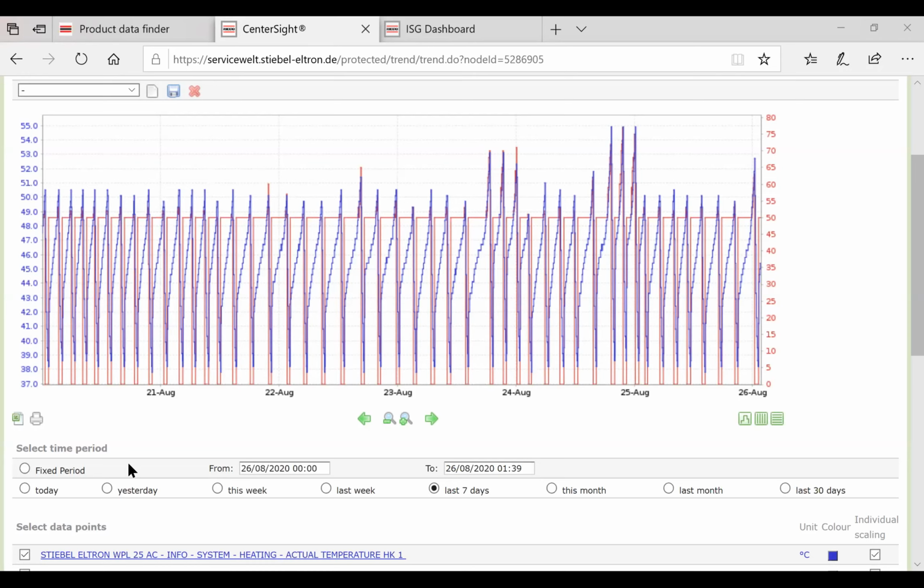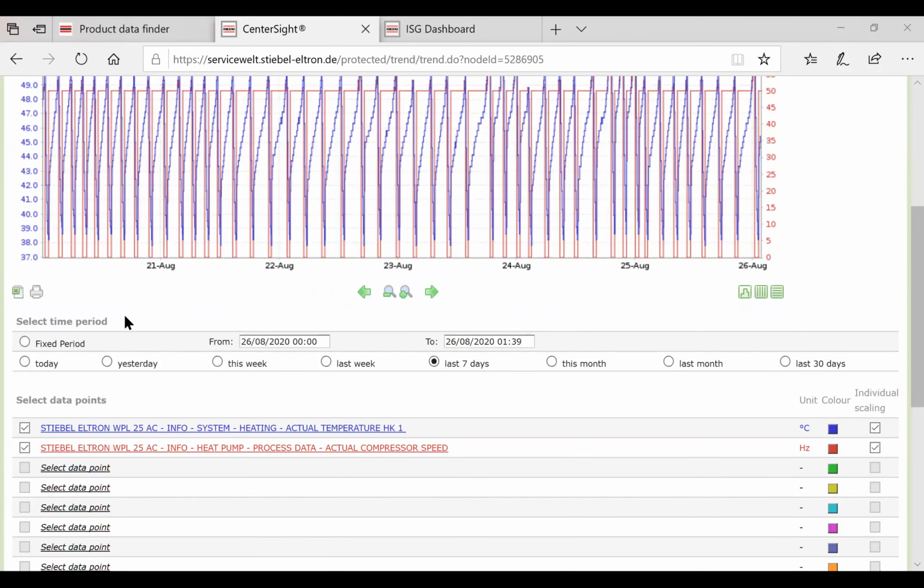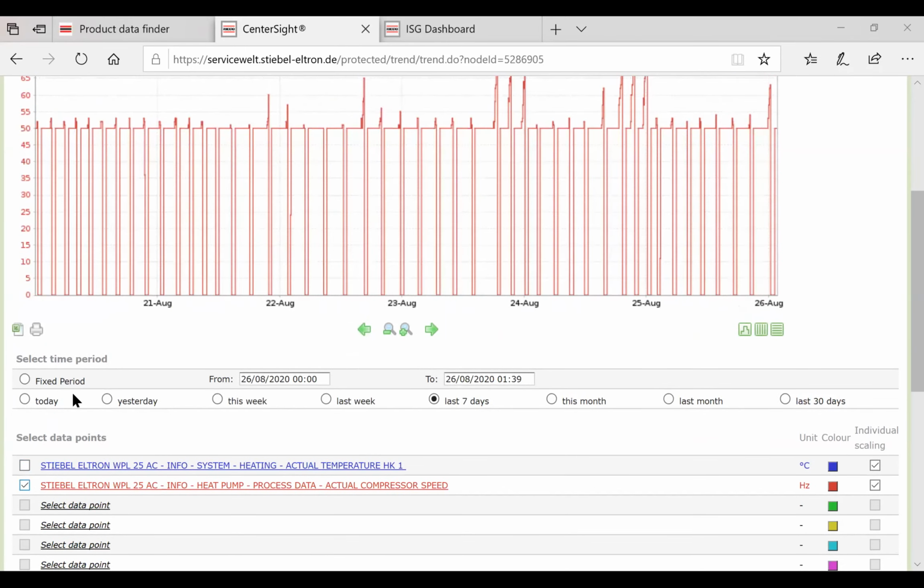So a lot of the time I'm looking at the actual temperature of the buffer tank and what the compressor is doing, but another very, very important one, just to answer your question, is water flow rate. I'm doing a troubleshooting one soon. In the next couple of sessions, I'm going a bit more in depth into troubleshooting and repair and bits and pieces.